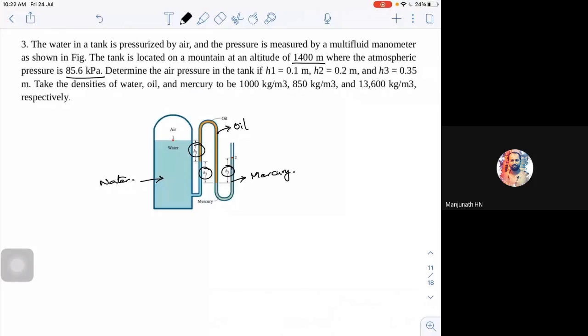So this is how usually we try to do it when we are teaching the manometric problem. What we try to do is get the datum between 1 and 2. Now look at this. What's happening here? The manometer is open to atmosphere. What is the pressure that's acting here? It is your atmospheric pressure.